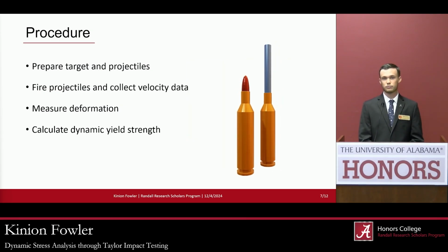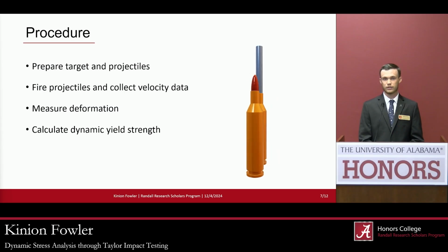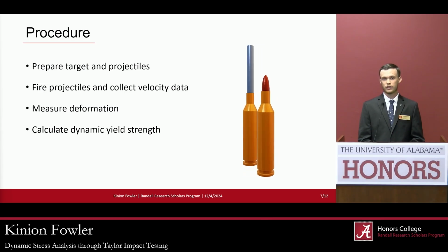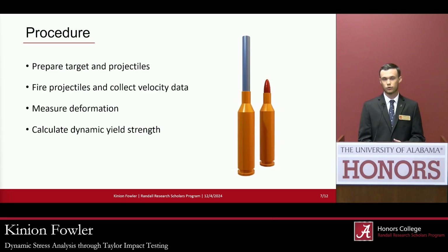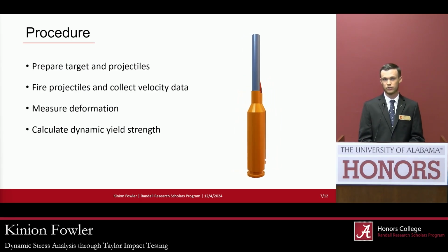So for each test, we first have to prepare our targets and our projectiles. The target has to be lapped to a smooth finish. That's to ensure that when the projectile impacts it, it deforms uniformly and does not deflect off in one direction or another.